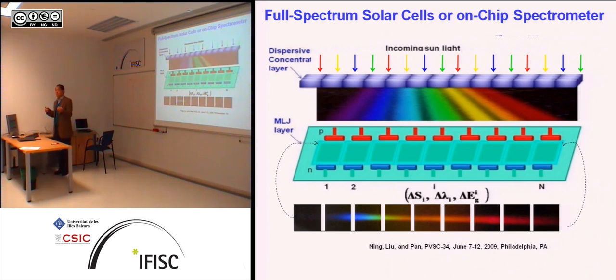Why is that important? For solar cells there are two major losses. One is thermal loss. When the photon energy is larger than the band gap, you get a lot of thermalization, so you generate a lot of phonons. That's heat. You heat the solar device and waste a lot of solar energy. The second problem is that if the photon energy is smaller than the band gap, the light is transmitted, so those solar photon energies are wasted. By matching the absorbing material with the right wavelength band, you optimize for both and minimize both important loss mechanisms.